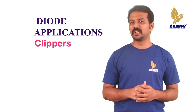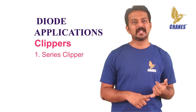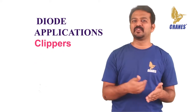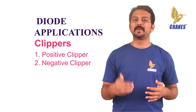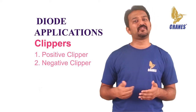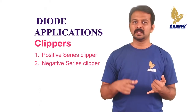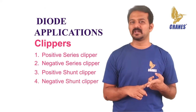Based on the diode configuration in the circuit, these clippers are divided into 2 types, the series clippers and the shunt clippers, and again these are classified into different types like positive clipper and negative clipper. So depending on series and shunt, positive and negative, in total we get 4 different types of clippers. The first one is the positive series clipper, negative series clipper, positive shunt clipper, negative shunt clipper.